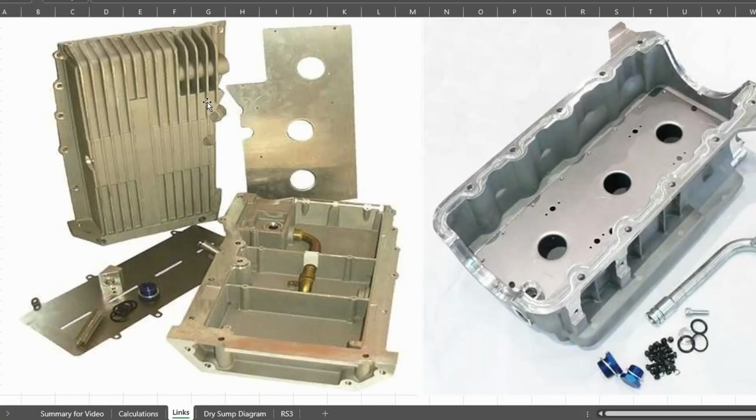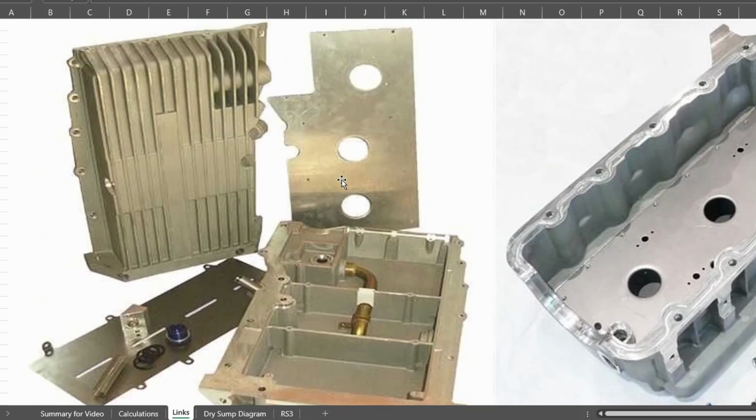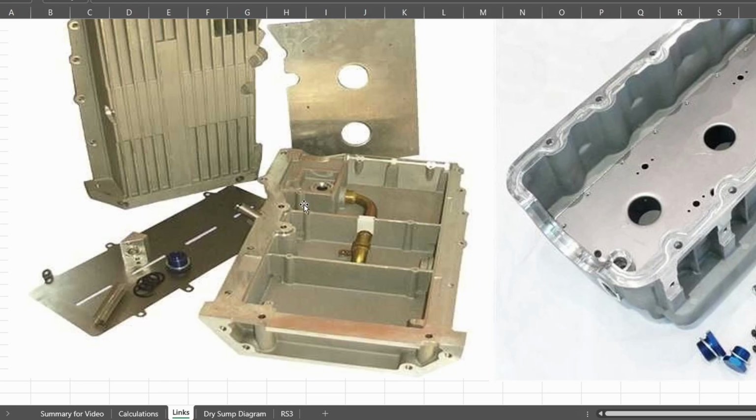You can see the one on the left, this sump is the one that I am familiar with, and with the sump open, you can see the sump has 3 partitions effectively, and oil is obviously stored within these partitions. It looks like at the bottom corner here there is an opening in between the partitions, and oil is allowed to fill in those areas.